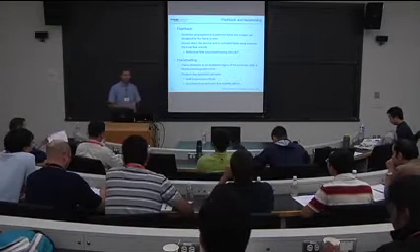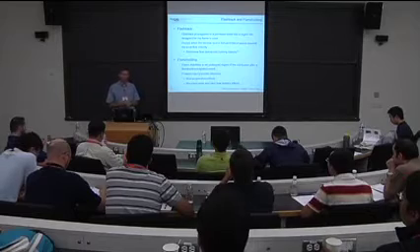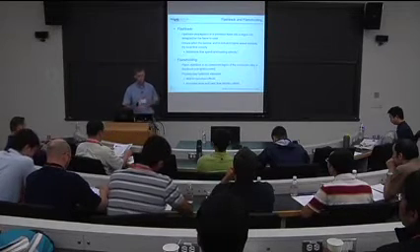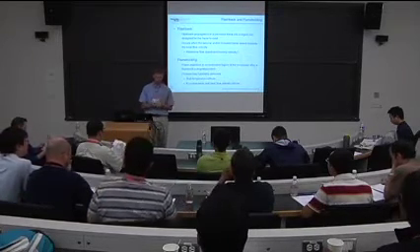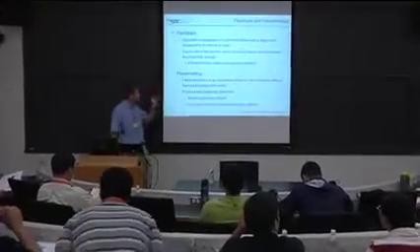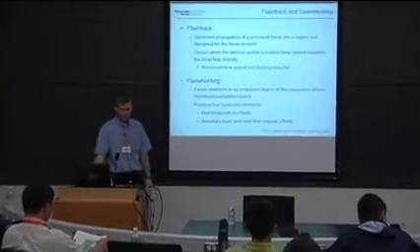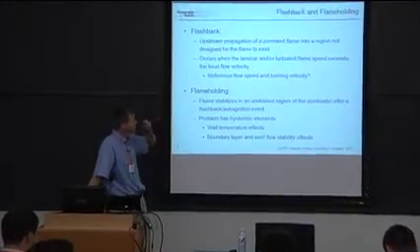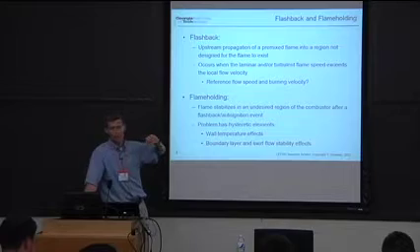Now, flashback is probably something, if you've taken combustion, if you've looked in Steve Turns' book or Professor Law's book or Glassman's book, they talk about flashback. What is it? It's the upstream propagation of a premixed flame. And the reason we don't like it is because it's usually into a region not designed for the flame to exist.